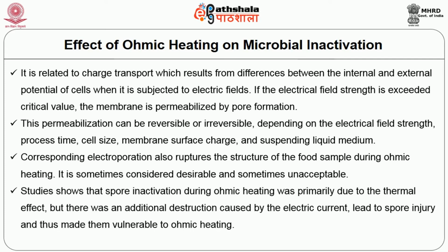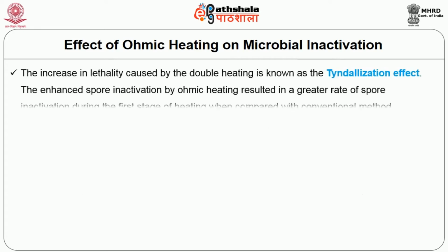Studies show that spore inactivation during ohmic heating was primarily due to the thermal effect, but there was an additional destruction caused by the electric current, which led to spore injury and thus made them vulnerable to ohmic heating. The increase in lethality caused by the double heating is also known as the tyndallization effect.